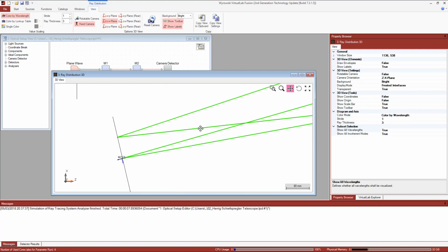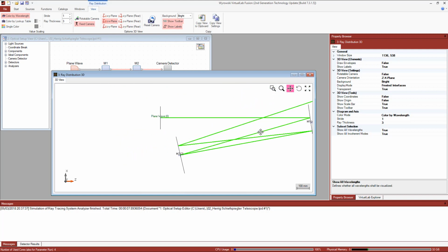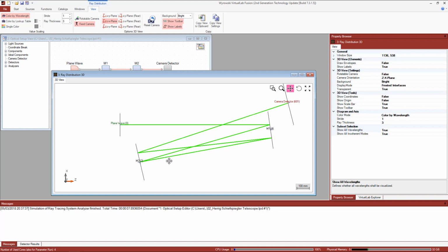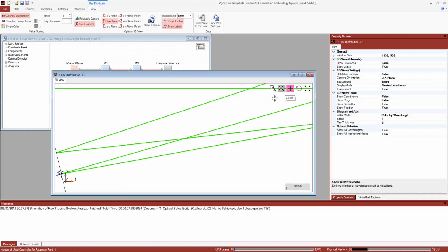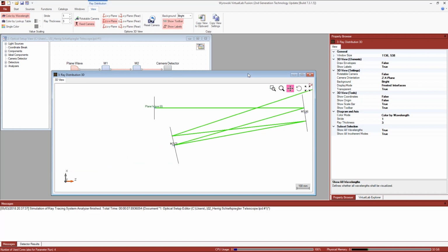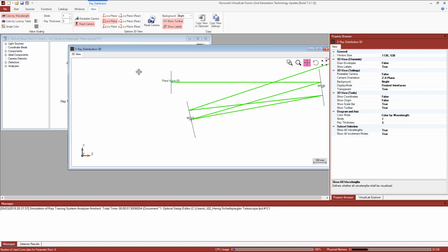Be careful, our reference coordinate system of channel definition is always the local coordinate system of the surface or components, but not the global one. Whenever users identify the local coordinate system of the components, channel definition becomes quite easy.